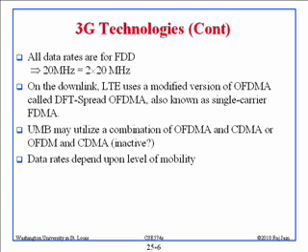FDD means frequency division duplexing. So you get some frequency down, some frequency up, exactly the same amount. So you get 20 megahertz down, 20 megahertz up. When we say 20 megahertz, it's really 40 megahertz. When I say 100 megabit, it is coming out of 40 megahertz, not 20 megahertz. They are not getting 5 bits per hertz, they are getting 2.5 bits per hertz.